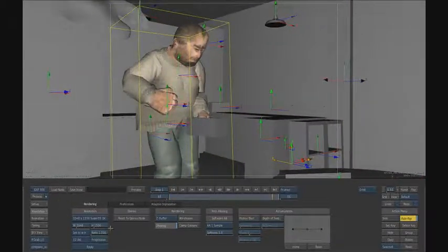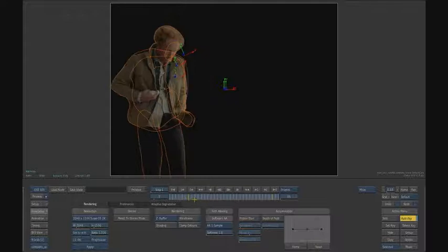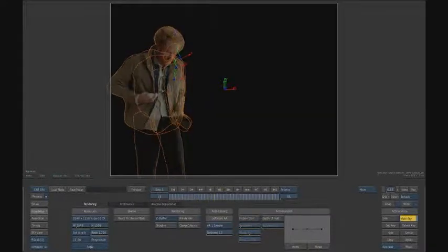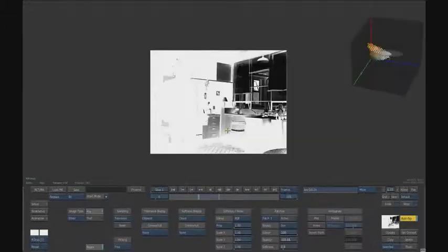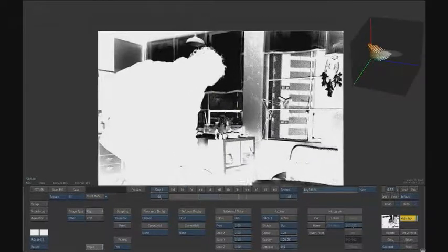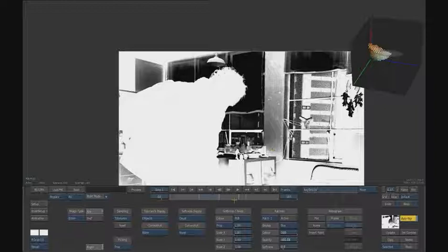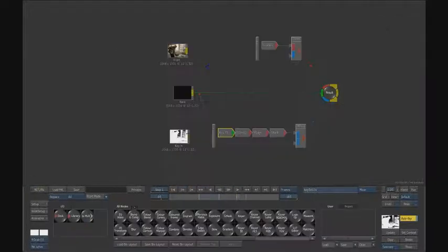The next step, of course, is to project the content on, and we'll just fast track a little bit here to look at a further along composite here, where we've dealt with a few situations that relate to edges. Here we're using a combined masking and keying technique here to get some edge detail dealt with, and we've actually pulled out some of our kind of big iron keyers here, such as the 3D keyer. What we're able to do here is to actually deal with the different pieces, including difficult edges like hair edges here in different ways. So you can certainly refine down, change the different sections between a kind of a keying technique and a matte technique here.